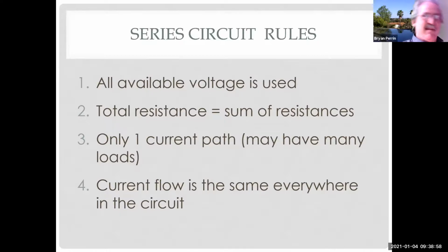Because again, any resistance in the series circuit is going to take voltage. Because we only have one current path. Although I can have multiple loads, there's only one path for current.